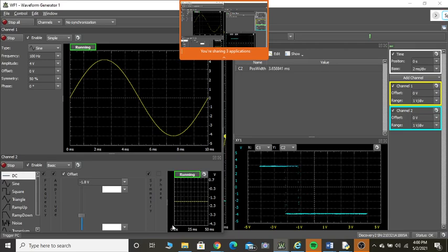Hello. This is zero, no? This is zero. These two are negative voltages. These two are negative voltages. So here the important thing is, for a given selected value of R1, R2, we are changing the reference voltage, noting what is VTH, VTL, that you can compare with your theoretical value.